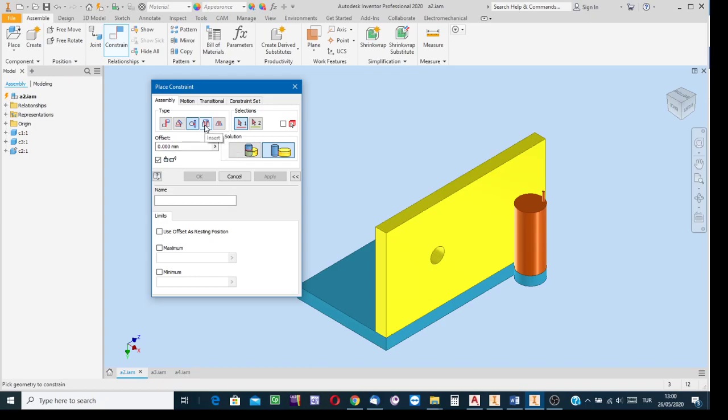If the entity is an axis, and the axis of one revolved feature is to be positioned with respect to the axis of the other, then use this facility. If it is applied with 0 offset value, then the axes will be in alignment, just along the same line of action. In the jargon, the objects are coaxial. And using this one, you can position one component as the symmetry of the other.